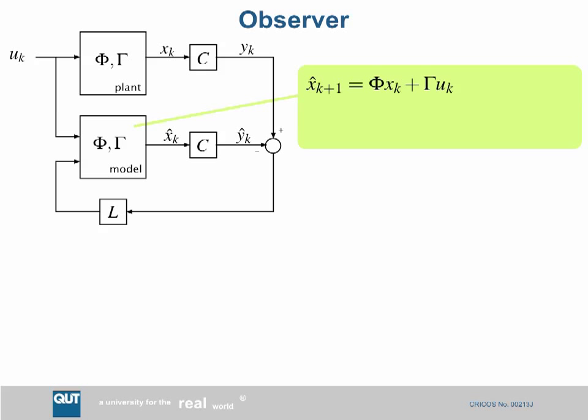But now the feedback term on the end says if there's a discrepancy, we multiply that by some gain and use that to push the state the right way. So we have to design this feedback bit, this L matrix, in such a way that this is stable and not unstable, and that would be bad. So that's what we're going to talk about next.